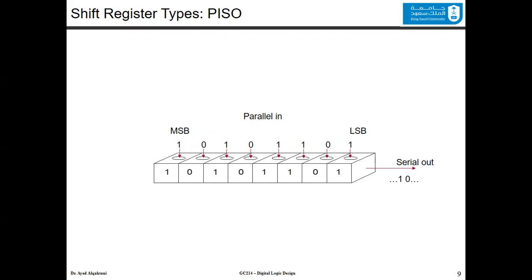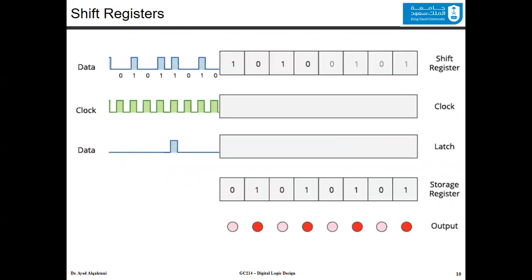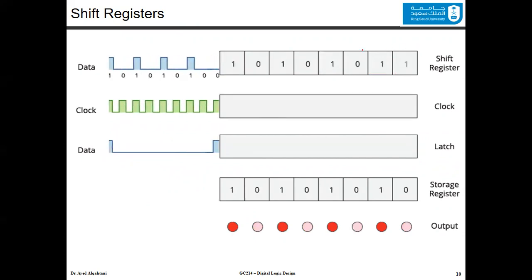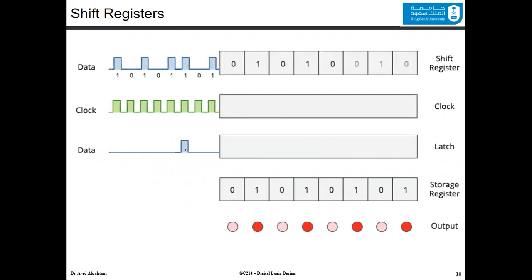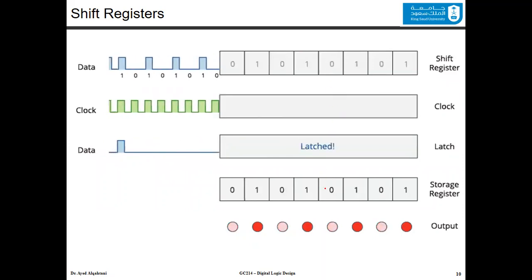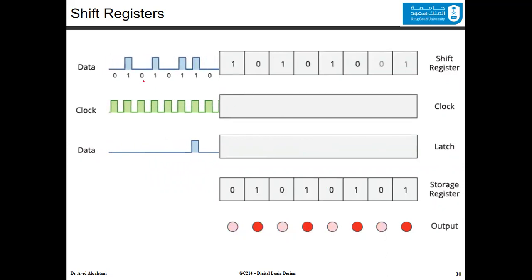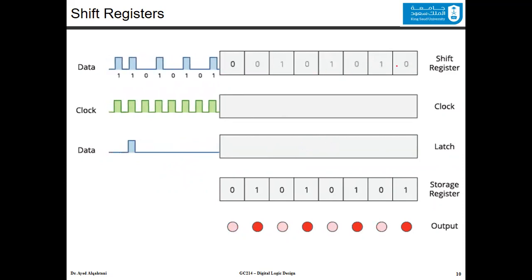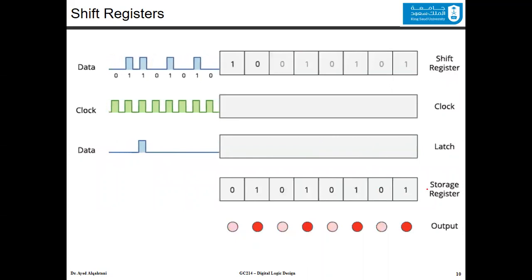To see one of the types in motion, this is the shift register, shifting the data bit by bit inside the shift register. And when the other data clock happens, or gets inside the latch, the value gets to the output. You can see that now we put the input serially, bit by bit, inside. And when the signal happens, in a parallel way, you get the output and save it inside the storage element.